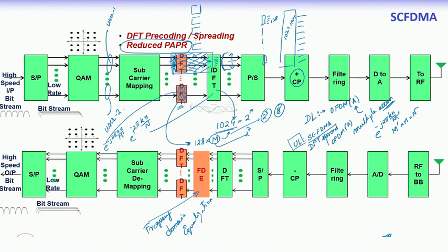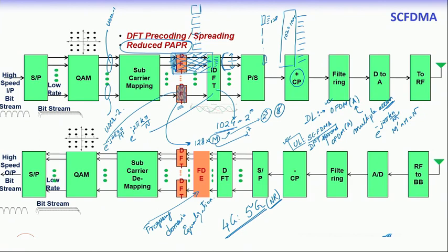So, this way in downlink OFDMA is preferred, in uplink SC-FDMA or DFT spread OFDM is preferred. In 4G, as well as the same thing is supported in 5G communications. So, when we look into the 5G NR, we do not have to revisit this particular aspect again, that this OFDM structure is followed in downlink, and in uplink this DFT spread OFDM is also supported because it would give a lot of benefit to low power devices to have a larger coverage and a better battery life.